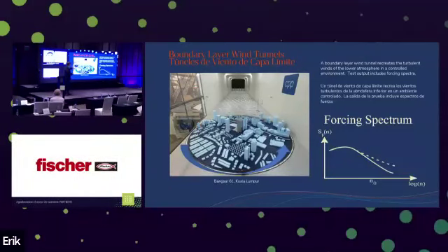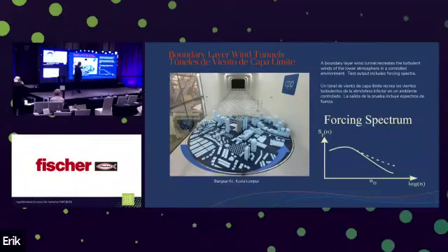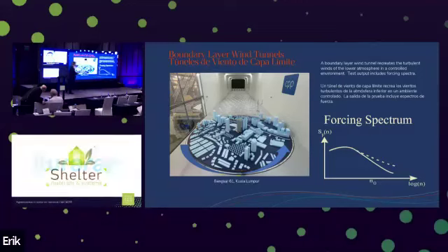We have a photograph of our boundary layer wind tunnel in Sydney. We have a subject tower in the centre of the turntable. And we have all the buildings within a 500-metre radius modelled. We can rotate that turntable to simulate different wind directions.